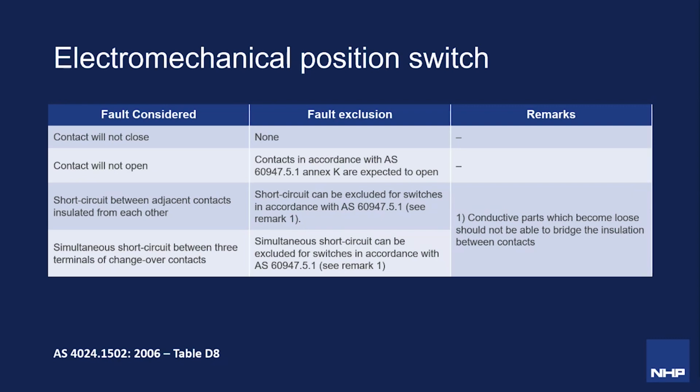Annex K in particular describes the supplementary requirements for direct opening action. If you've seen in our Safety Essentials series and also in the previous session on interlock switches, direct opening action is one of those well-tried safety principles which make components safe, which it relies on direct mechanical action to force the contacts open rather than reliance on springs or other non-resilient means.